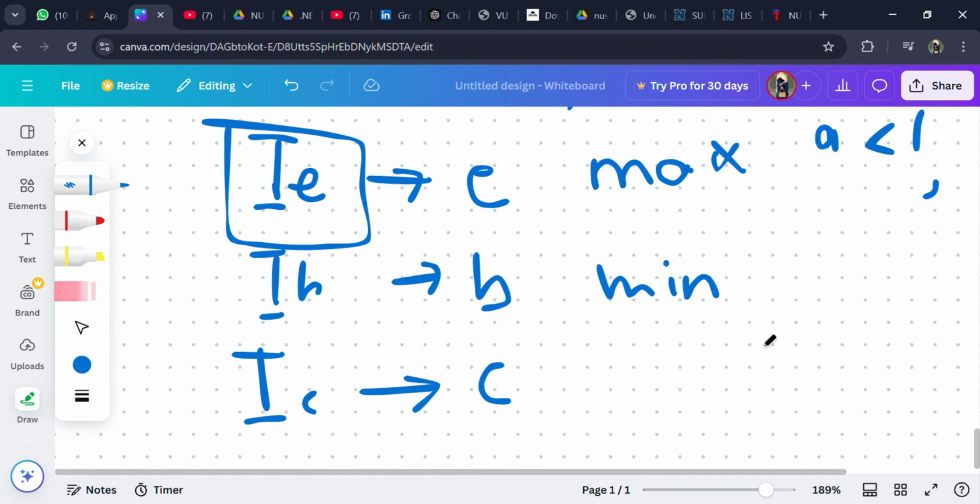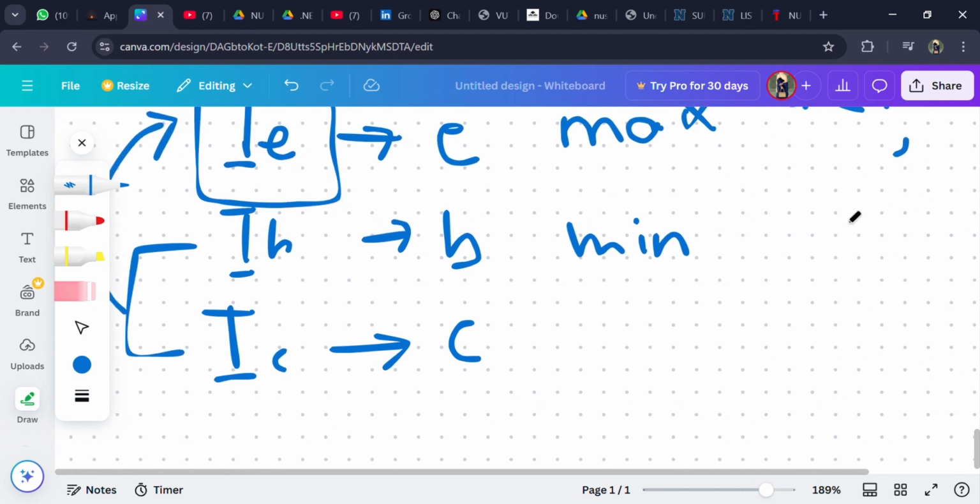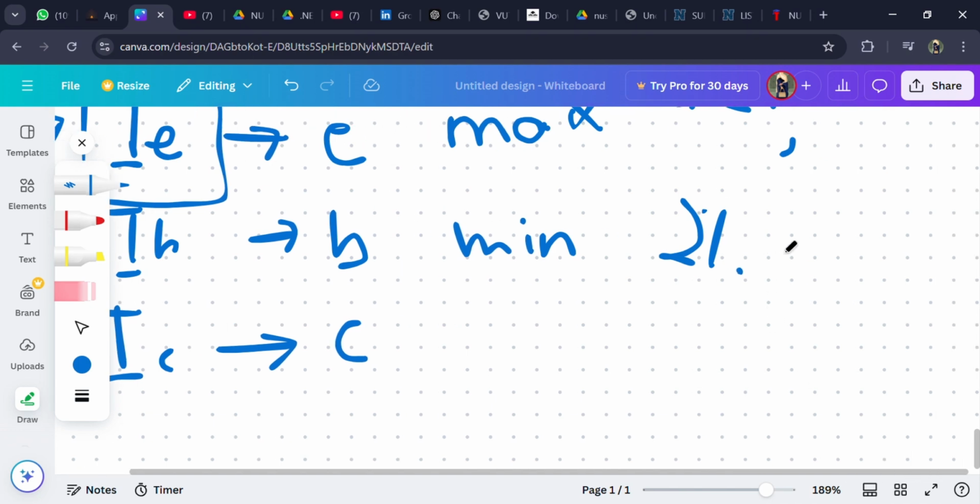And if we add IB and IC, we get the actual amount of current that was flowing. 100% of the current starts flowing from IE, 2% to 5% drops here, and 95 to 98% reaches the IC side, the collector side.